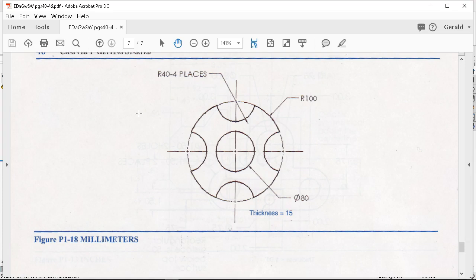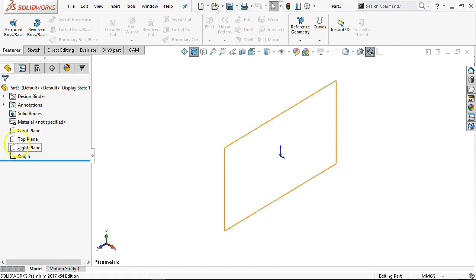You have all of these tiny decisions as you're going through, picking your strategies, things that you're familiar with, things that you're experimenting with, and the building blocks getting to the next level. Drawing this, I have the choice of staying with contours and regions and just generating all of the geometry and picking what I want to extrude. Or I can go back and I can trim. So we'll look at it from both sides.